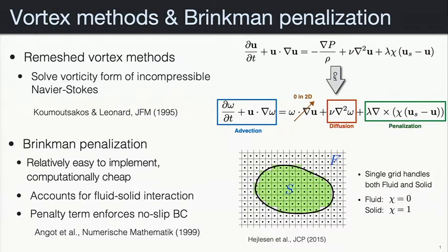Now you can solve all of the grid points as if it were pure fluid. And this forcing term, F, that we talked about, basically forces the occupied grid nodes to behave like a solid. Does that make sense? It might be a little confusing, so ask me if something's not clear.